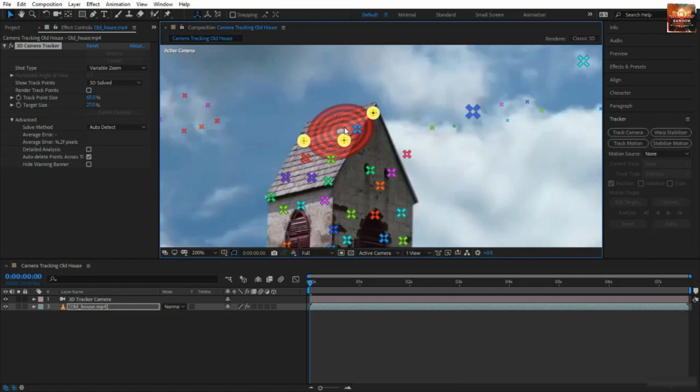As soon as you click, you can come in the middle, in the eyeball, and start moving the target. Now, if you move the target, whatever you create after that will be set on the target. The idea here is you have a plane defined by 3 track points, and the target is just moving on the surface of this plane. So actually, this movement over here is not in 3D, it's just in 2D. You could say X and Y, for example, but still in the same plane. I'll just position it over here.